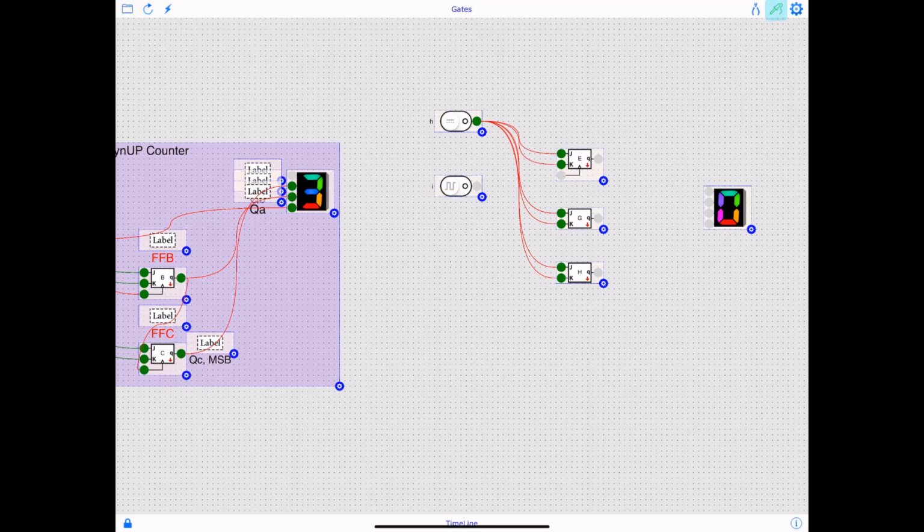Actually, I'm going to use a different color. If I click on this wire looking thing on the top right here, which is the green icon, and let's say I want my clock in green, so here I come, and this is my clock. Remember, the output of this flip-flop needs a clock also, and also this flip-flop. Let's now connect the output of this one to the clock of this, and the output of this flip-flop to the clock of this right here.